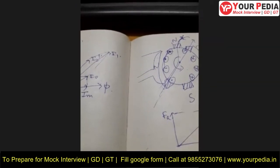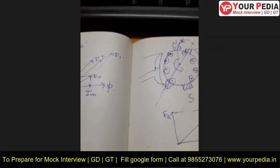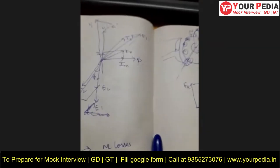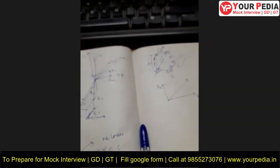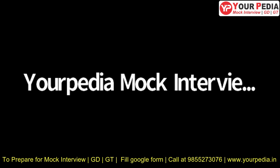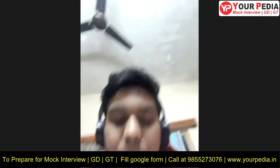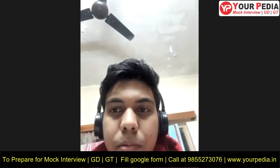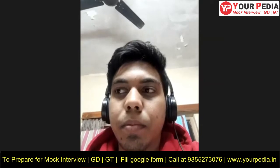You have good knowledge of the machines, and all the questions that I asked were about the phasor, then one numerical, and the phase notation. And one thing that I asked about the phasor: suppose there is a star connection and there is a phase shift of 60 degrees in one transformer, then how should the resultant be drawn?